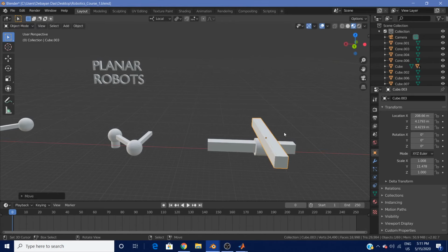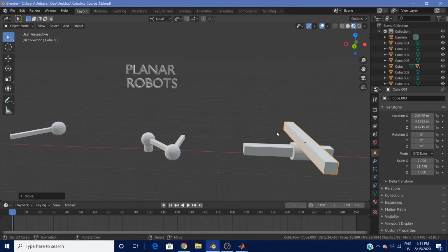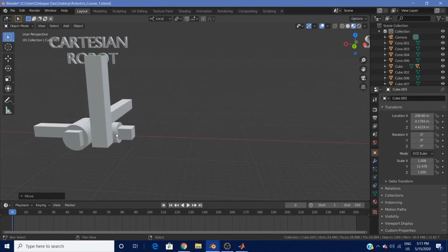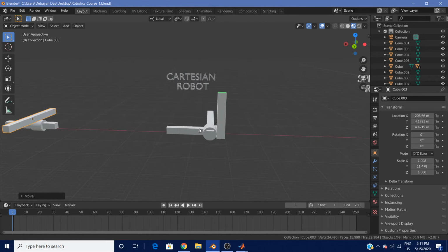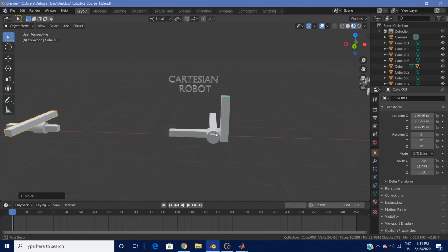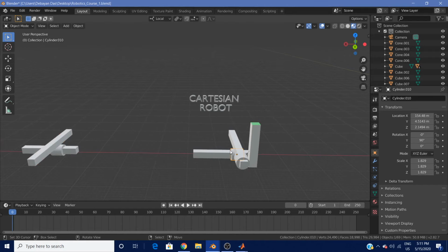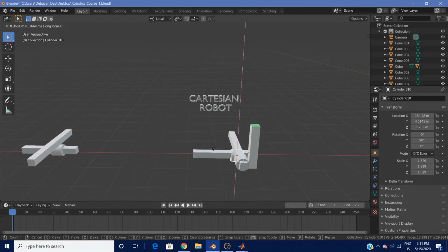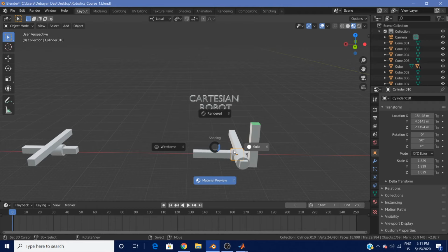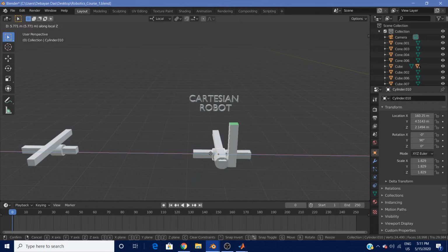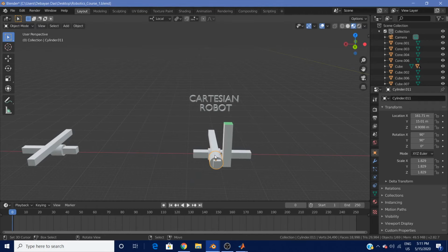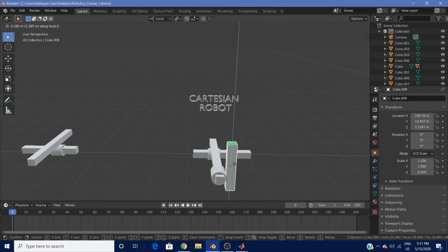And that's what we saw for planar robots, and they could be of a third type which could have one revolute and one prismatic joint. But to reach the third dimension, you needed another joint which could make three more categories of robots. So the Cartesian could move anywhere along the x, the y, or the z,